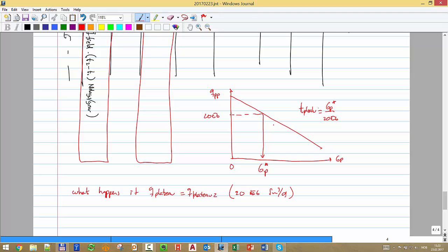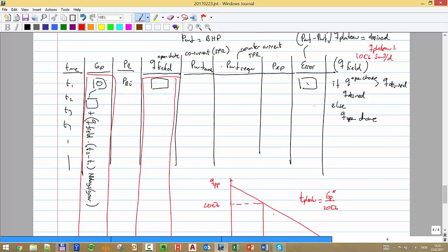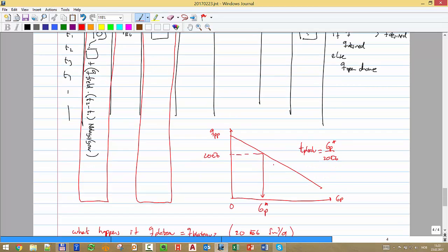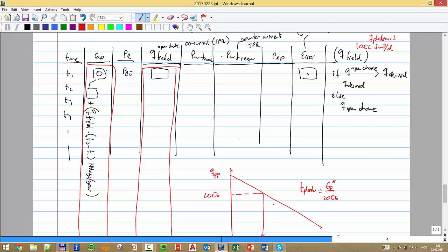it was calculated independent of the Q plateau. If the production system doesn't change, the number of wells don't change, the reservoir doesn't change, the IPR, the TPR, why should the potential change if I'm just changing the rate? It doesn't change, right? So it doesn't matter if I calculate it for one case, I can use that later for all the other cases. And that's what is very beautiful about the potential. You don't have to run these calculations anymore. Okay?